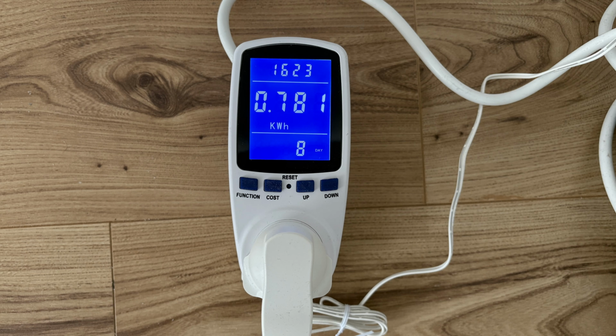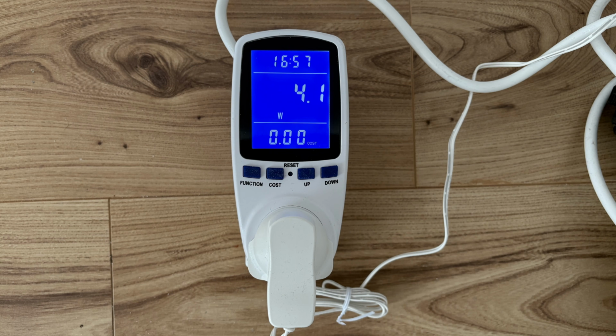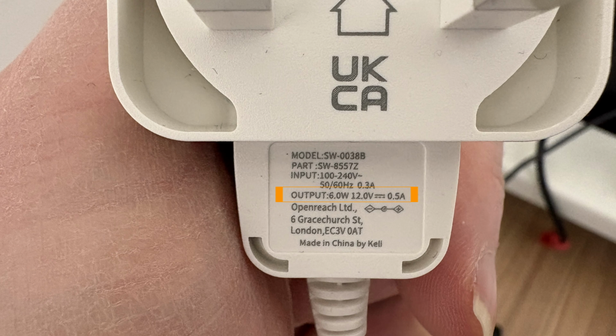In total, it consumed 0.781 kilowatt hours over the 8 days. Divide that by 8 and times that by 365, and I get roughly 36.63 kilowatt hours per year. At the time of check-in, it was using around 4 to 4.1 watts of power. The highest monitored was 4.4 watts. Lastly, the power adapter is rated up to 6 watts at 12 volts and 0.5 amps.